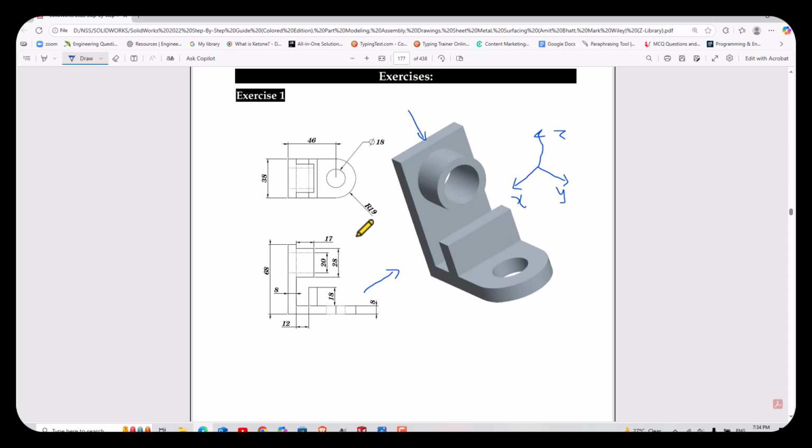Let's take a look at the diagram. And we can see that the outer circle has a diameter of 28 and the inner has a diameter of 20. That means that in this direction, the distance from this part here to this part here is half of 8, which is 4. So it means this part here has thickness of 4 millimeters. Because 4 here plus 20 plus 4, that will give us 28.